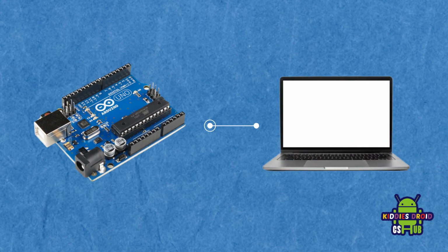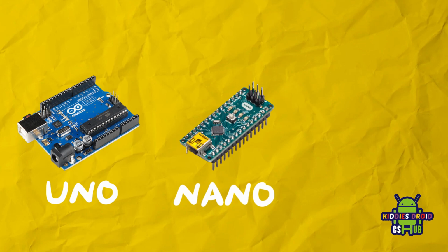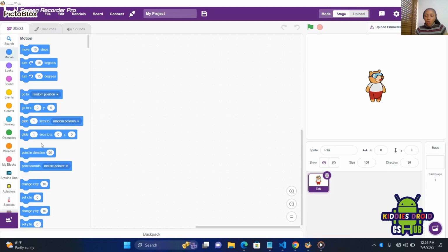So next, let's connect our Arduino board to the computer. Arduino boards come in various types such as the Arduino Uno, Arduino Nano, or Arduino Mega. Grab your Arduino board and connect it to your computer using a USB cable. Make sure the cable is securely plugged into both the board and the computer. So I have my Arduino board here. I'm using the Arduino Uno, and this is my USB cable. I'm going to be connecting my Arduino board to my USB cable and connecting it to my computer. Once it lights up, it means that it is successfully connected.